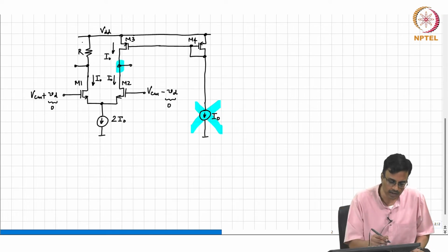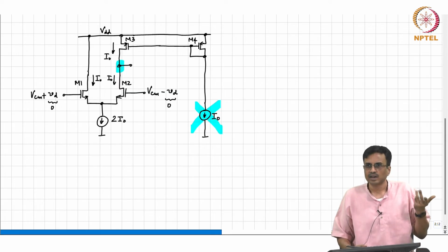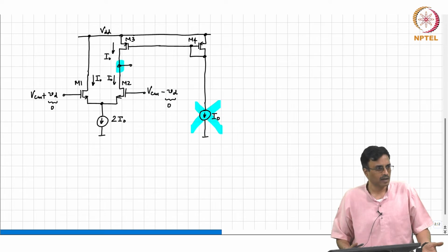Okay. So, if we do not need this R, we might as well connect it to VDD. All right. So now you can see that M1's drain current is simply doing nothing, it is just connected to VDD. You might as well put it to work. What does M4 need? And what is M1's drain current doing? Nothing. So, what do you think we can do?